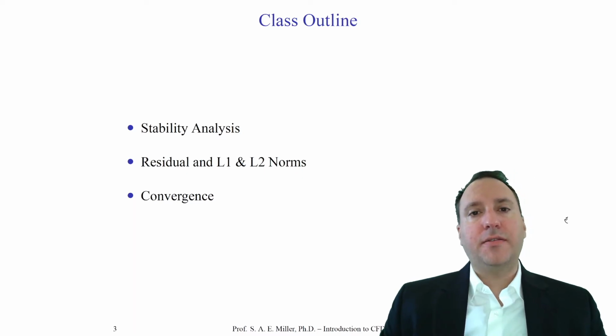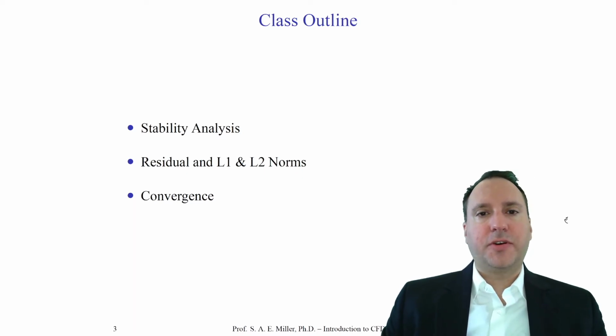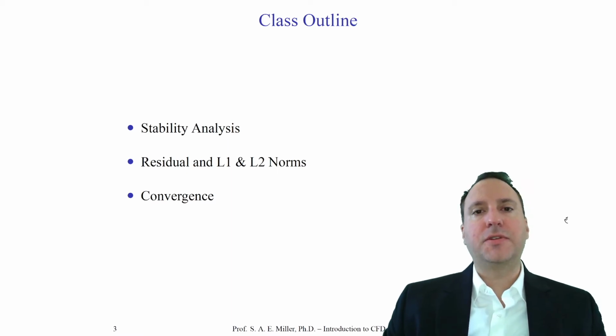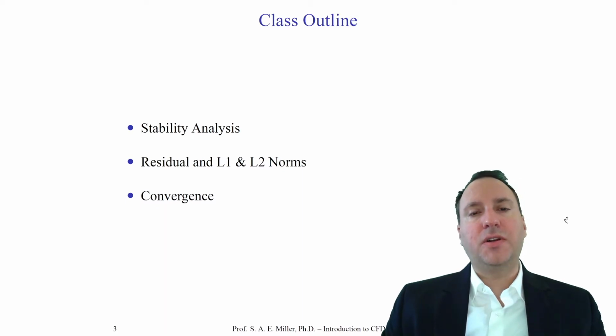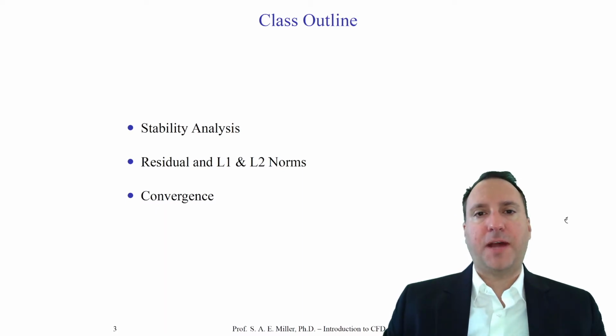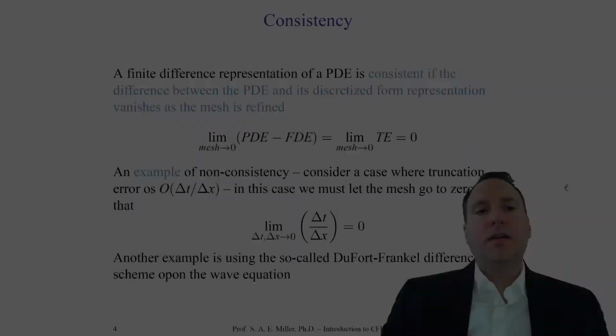norms, and the convergence. Stability refers to a characteristic of a particular solver numerical method, in that as it progresses towards a solution, it either blows up or becomes stable and moves towards a particular solution, which is what is referred to as convergence. If the solver is stable, approaching a particular value and well behaved, then we might achieve convergence, which is the property that the solver is not blowing up. We'll look at these in a little bit more detail with some mathematical definitions and examples.